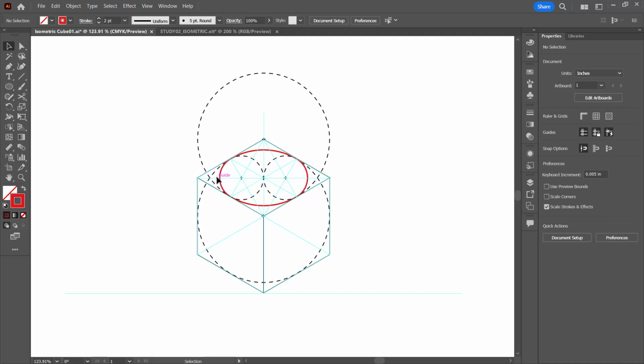Same thing over here. We would go from here to this point and then draw our arc from point to point using that as a radius, right? That creates those two arcs. Then we would take this one from our corner points and do the same thing. We'd create a radius all the way to that midpoint, and draw. So again, you can see where that full circle would be. That's what these dotted lines I drew are.